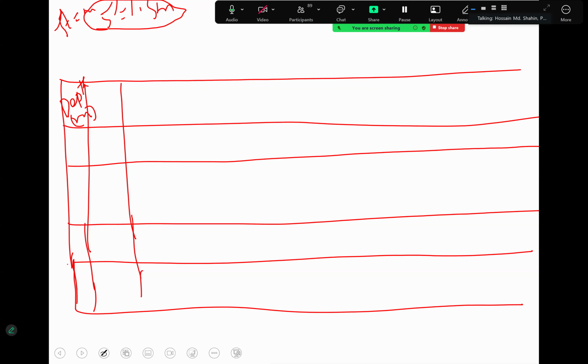Those who only have the soil report have the depth given in feet, so you have to write it as meters. So consider 5 feet equal to 1.5 meters. Then SPT N value, and you consider this is N60.